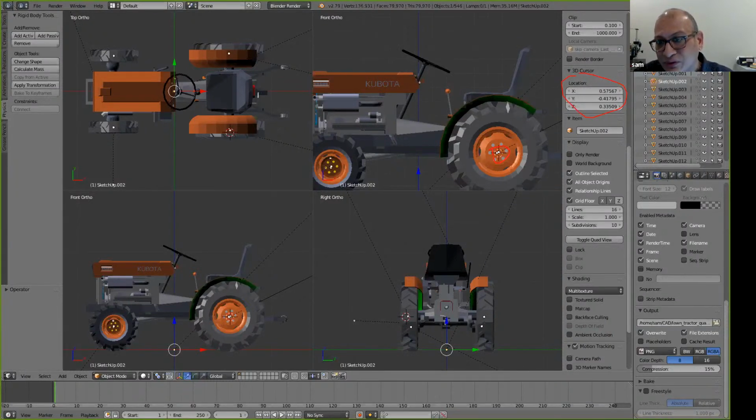My CAD 0, 0, 0 is right at the center, and I wanted to see how far off the center of the rear wheel is. That shows me that you are far out, about 0.55 meter in this case, assuming the whole unit is in meter. So my X is 0.55, and my Z is, I can see, 0.33.